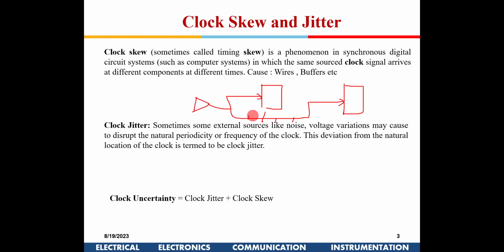That can cause clock skew. Also, when we do the routing and placement, there could be buffers in between. Many buffers in this clock, because there could be some distribution like this. This clock is coming directly here, whereas in this path the clock might be going to various flip-flops within the chip. So there could be some clock distribution network, and there could be additional buffers placed in between. This again we saw in the last class in the clock distribution system.